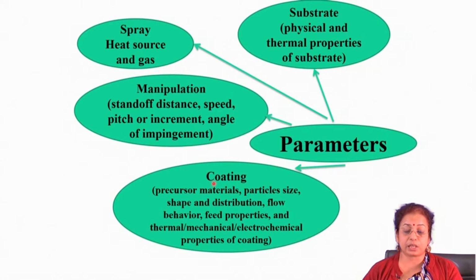If it is, for example, corrosion resistance application, then you can use some coating which is highly inert, or maybe you can also use one highly noble in nature. On the other hand, if that particular environment is not really so aggressive, then you can also think of polymeric coating. So, coating material choice is very important, and that is the first thing which you should do prior to choosing this particular technique, because which coating material you are going to coat onto the surface of the substrate, that dictates the coating technique you should apply.